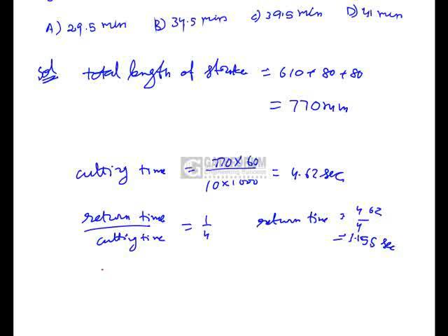And here the total time to complete one double stroke, that is both return and cutting strokes, is given by 4.62 plus 1.155, which is equal to 5.77 seconds.